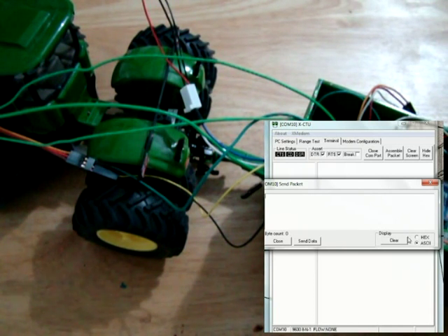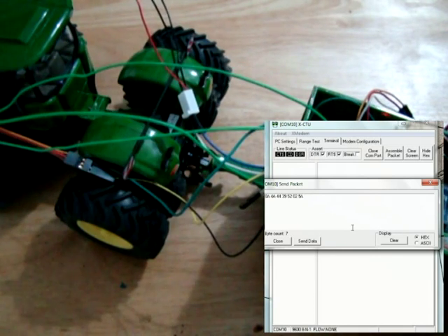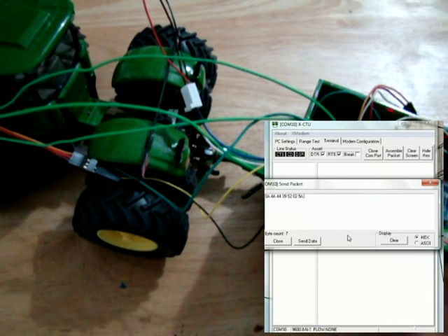From here we can type in our command string, so we'll go hex 0A, which lets the tractor know a command is coming. We've given it the ID JD9R, and if we go back to hex, there are the hex values for JD9R. We want to do steering, which is 02, and we want a test value. We'll start with 5A, which is 90 degrees in hex. So we switch on our tractor. It's now ready, and we send our command.